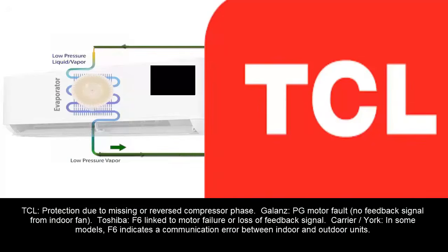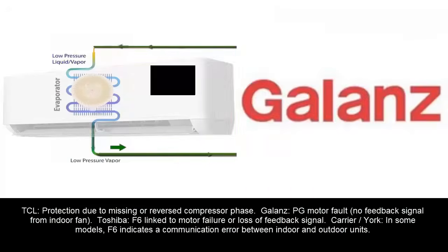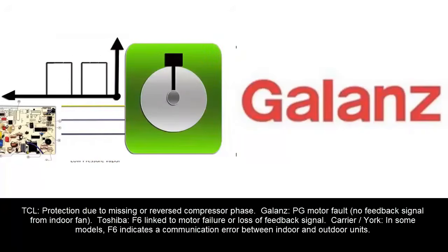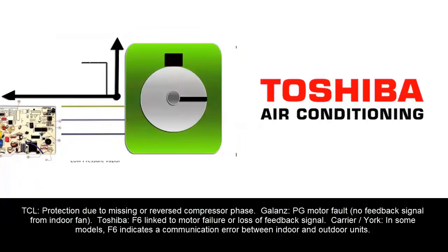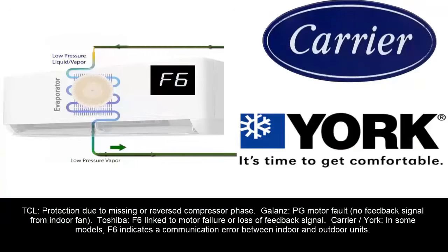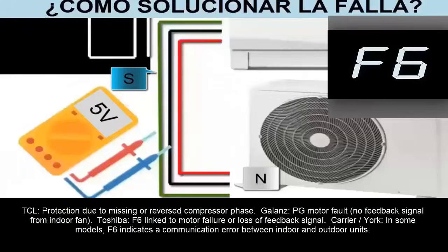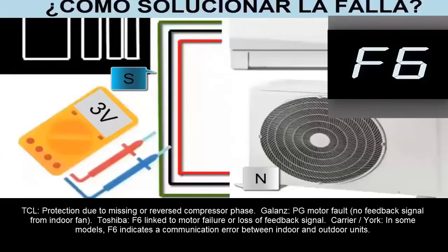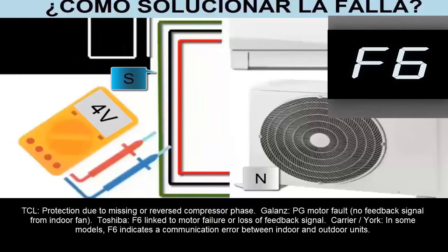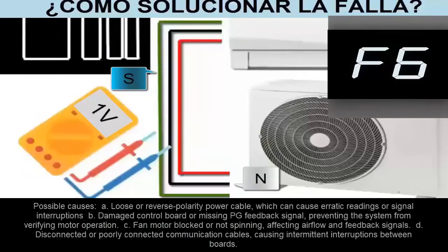Associated brands. TCL, protection due to missing or reversed compressor phase. Galanz, PG motor fault, no feedback signal from the indoor fan. Toshiba, F6 linked to motor failure or loss of feedback signal. Carrier, York. In some models, F6 indicates a communication error between indoor and outdoor units.